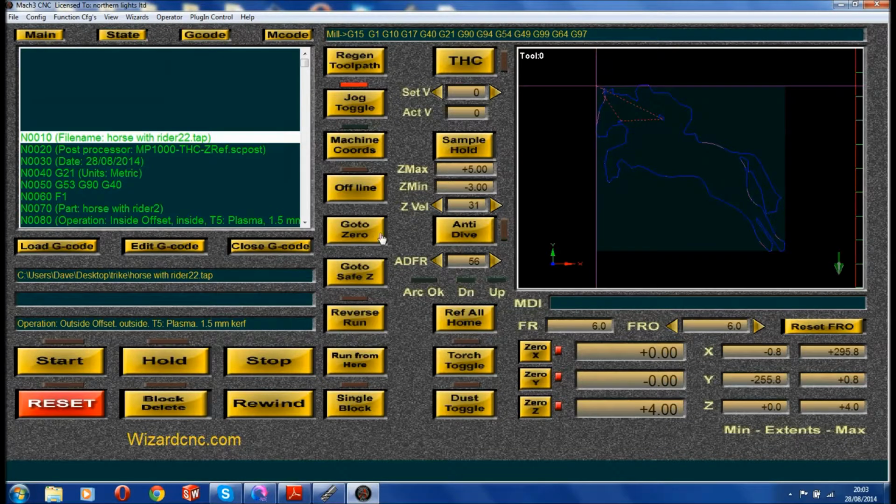Let's bring your sheet in. As you can see here, that's where your torch is placed, on the top left hand corner of your sheet. Your zeroed X and Y. If your Z's miles away, drop it down to near the plate and zero that as well. And I'm just about to do that. In fact, I'm alright. It looks around about what it's saying on my DRO.